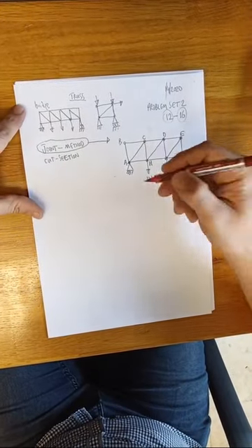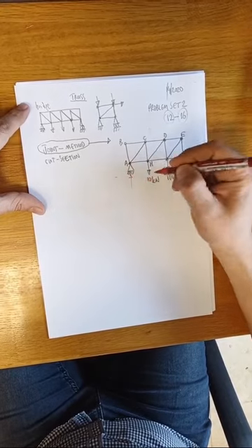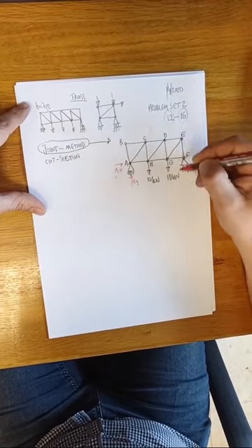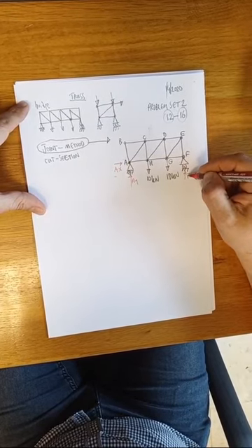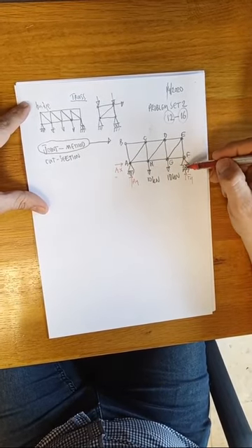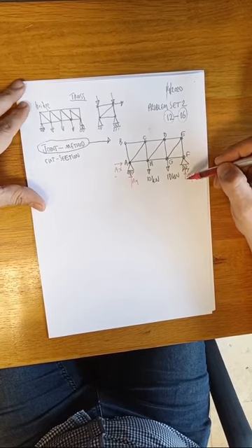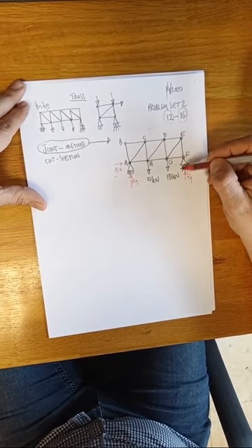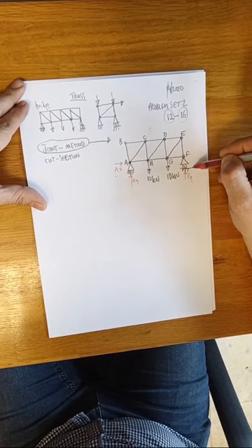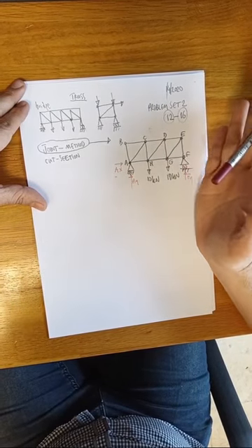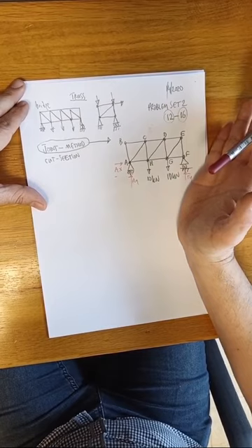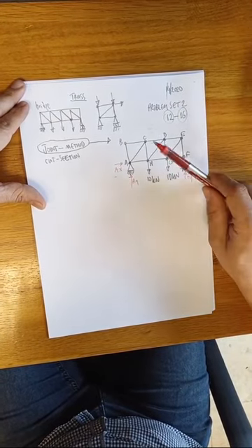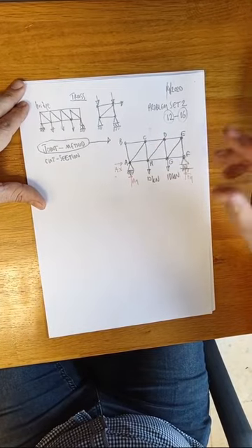First of all, introduce the reaction forces like this. This is AY, this is AX. And this is FY. As you see, it is the roller support. The reaction is only in the normal direction with the surface of the roller. You see the roller here. If the roller is in some other direction, maybe some inclined direction, the reaction must be normal to the inclination.